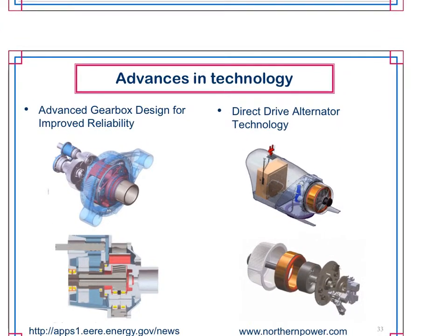The downside of direct drive technology is your generator, which is here, is going to be putting out whatever the freewheeling frequency is, and that means you have to run all your power through power electronics. Whereas the GE turbines directly connect their generator output, so most of their power goes directly to the grid, but that's not practical with direct drive. So you need big power electronics that aren't as efficient as direct connections, and are expensive to operate and maintain. So you do see a few, but they're not nearly as popular as the gearbox getting it close to speed.